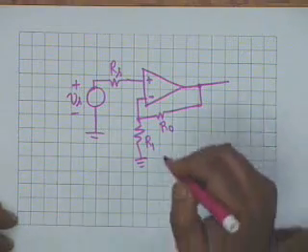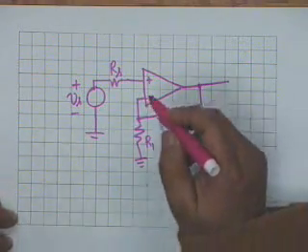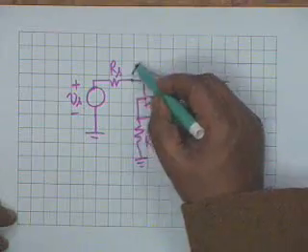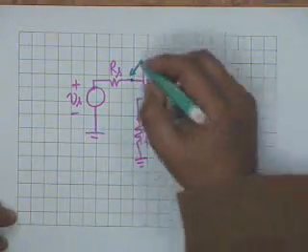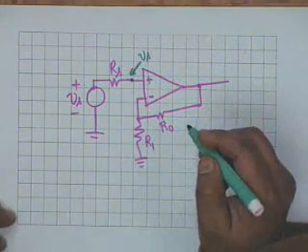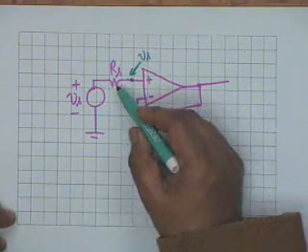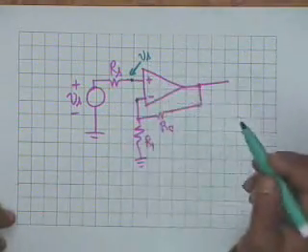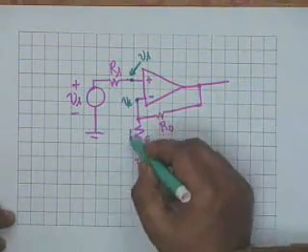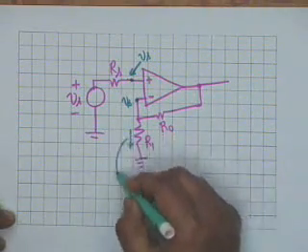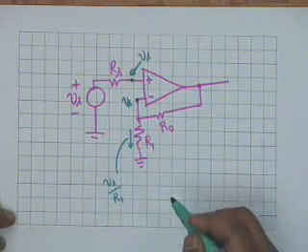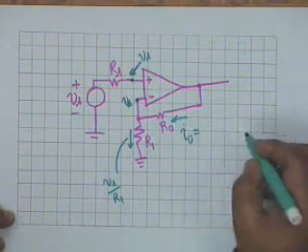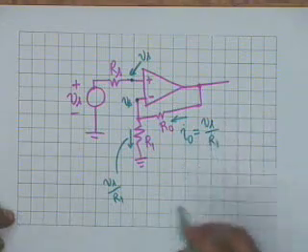All right. Now what would be this potential for the analysis of this circuit? Vs. Why? Because the OpAmp does not take any current, so there is no drop in Rs, so Vs comes directly here. Is this point clear? Yes, all right. If this is Vs, then what is this potential? Vs. Then what is this current? Vs by R1. All right. Let's call this current I0, then I0 is Vs by R1.